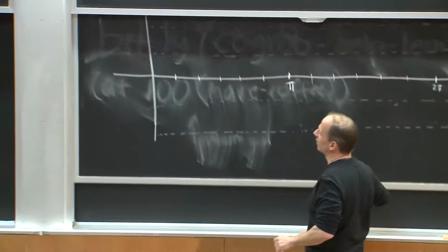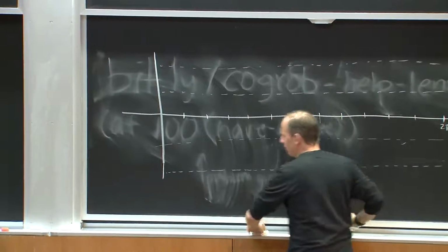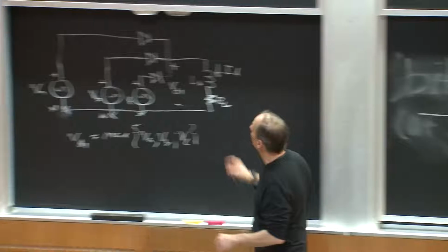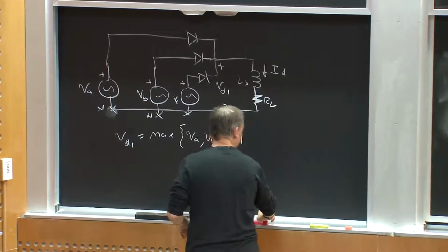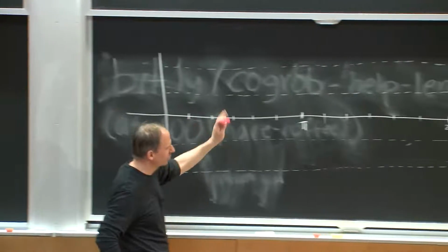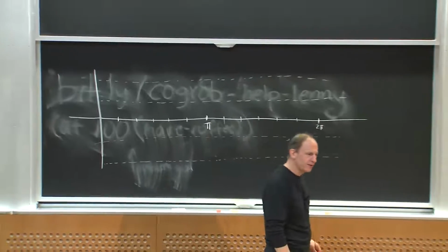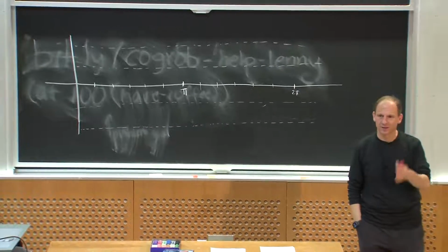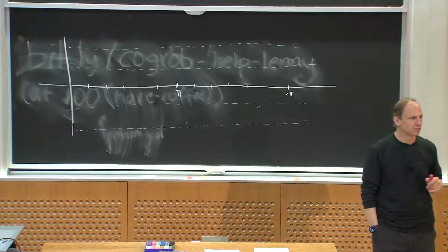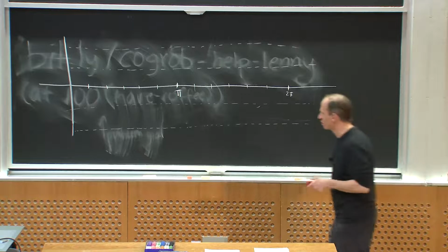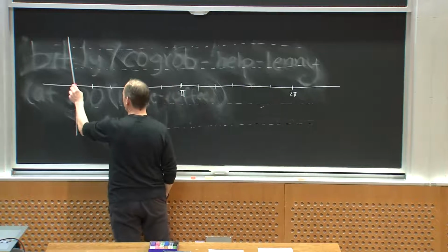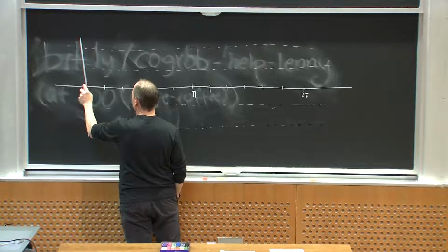So let me plot these things. If I said VA was a sine wave, okay? So the sine wave looks like this. And just for reference, when I plot these things for three-phase, it's often convenient to break things up into pi over 6 intervals, 30-degree intervals, just because it comes easy to plot things. So if I took VA it would look like something like this.